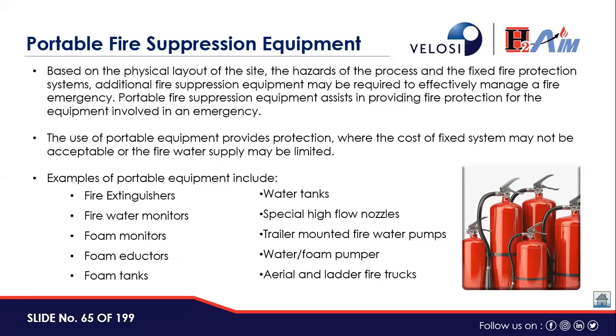Okay. Next question. Can you please explain what is diking? Dikes are the bund walls, like when the tanks are built, 3, 4 tanks or 1 tank, if the tank leaks, you don't want the liquid of the tank reaching everywhere. So you build certain bunds or walls, that's called diking. So the fluid remains within a controlled area rather than spreading everywhere in the facility.